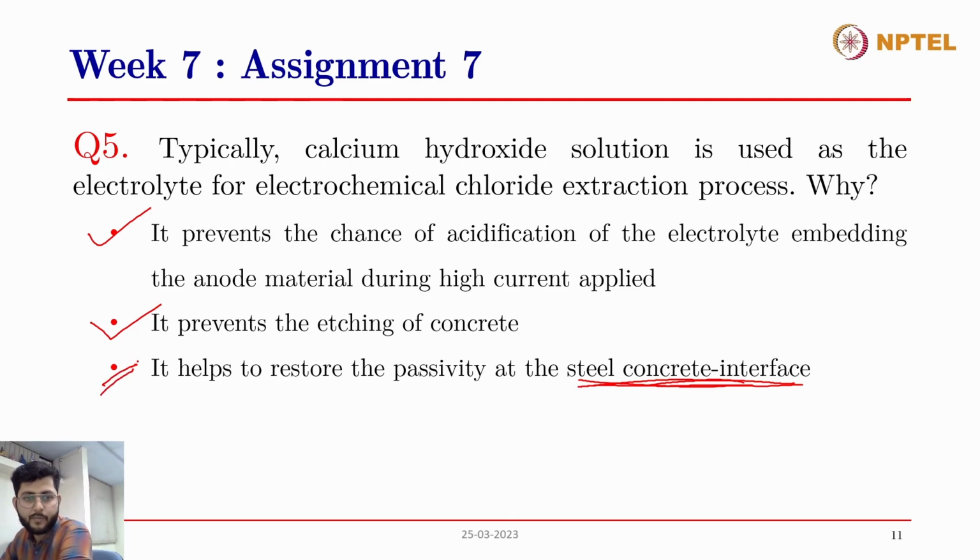But using the calcium hydroxide solution will restore the passivity at the steel concrete interface. How? I guess you're referring to the case of electrochemical realkalization. But here also you are using calcium hydroxide solution. So the third one is also correct.